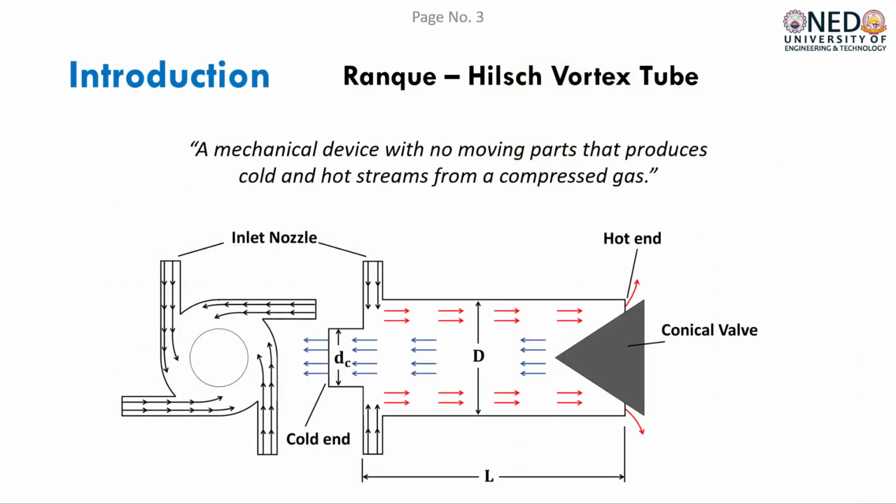Ranque-Hilsch vortex tube is a thermofluidic device that was invented by Ranque and optimized by Hilsch for practical use. This device has no moving parts and comprises of vortex generator at the inlet and two exits for cold and hot streams at opposite ends.